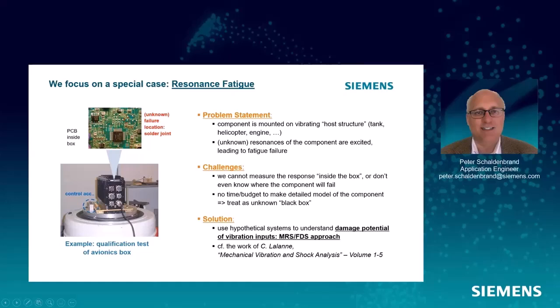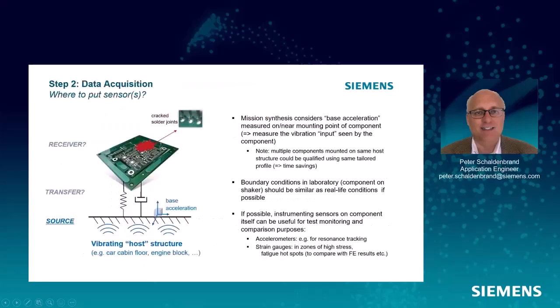Also, it's either very time consuming or difficult to take this input and monitor what's inside that box to model it. So what we're going to do is use a hypothetical system. We're going to use a base input into the structure, and we're going to make a model of the structure to predict what's going on inside. And this is specified a lot in Lalanne, one of the references in the presentation, on how to do this in detail.